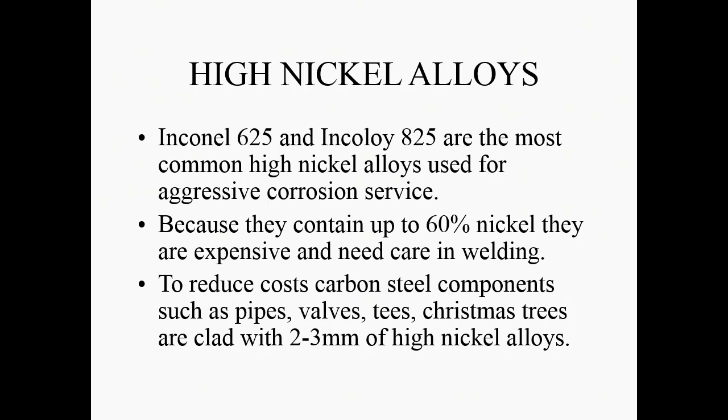They're nickel-based alloys. They can be welded, but they are very, very expensive. I mean, these are the sort of alloys that are similar to what you make gas turbines out of. And you have to really want to use these alloys if you can do it. Certainly on a pipeline, they're not really economically viable. But you can use a layer of this nickel alloy on the inside of a pipe or on the inside of a valve as a clad material or as a liner. And so a 2 or 3 millimeter sheet of the nickel alloy can be put inside the pipe to actually give you the performance that you need.